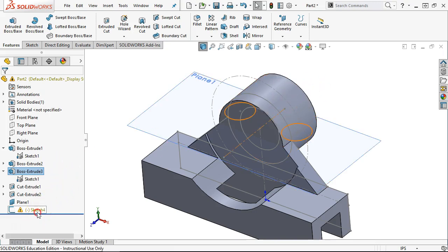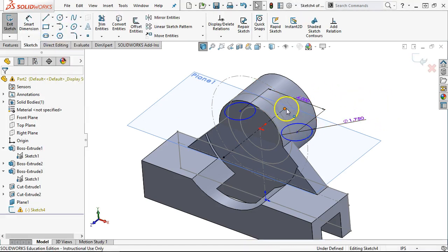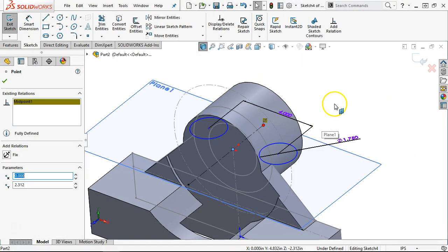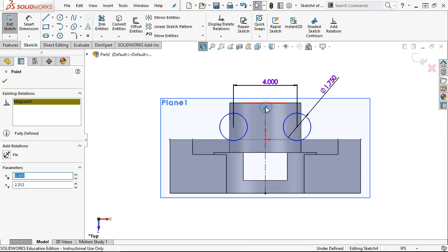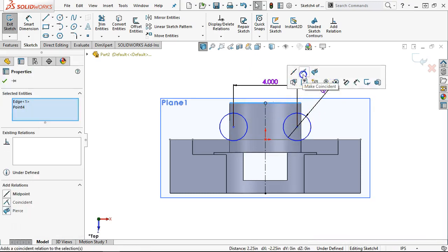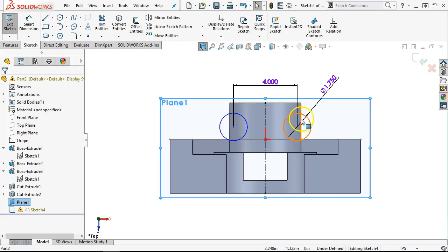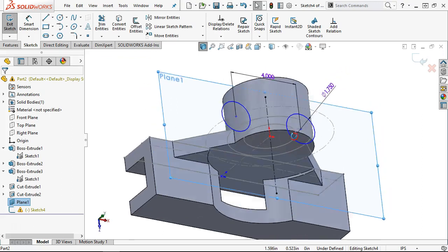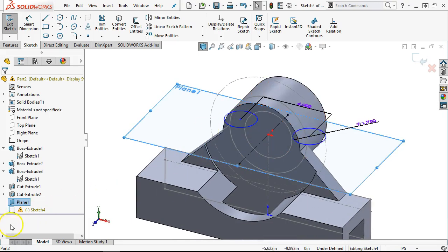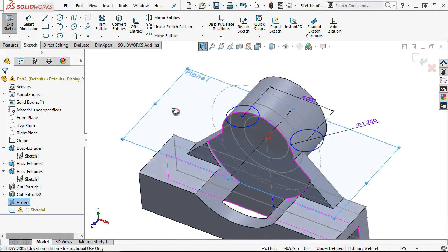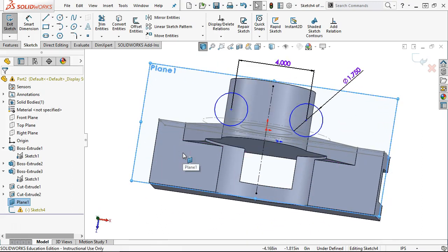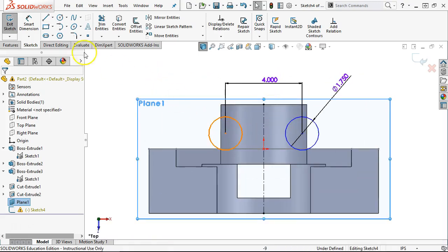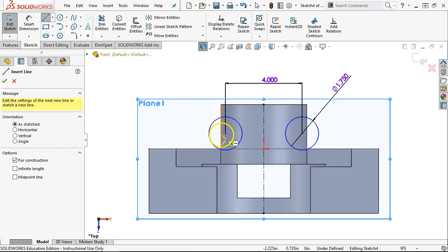Well, not surprisingly, the sketch picked up because that geometry changed a little bit. I'm going to end up with one dot in amber because that midpoint now is not able to calculate. So we'll just delete it. It can go back to being coincident. Don't really care where it comes back to. So we left off with 4 inches, and then we're pretty much centered. So the 1.63. Yeah, the tough decision is, am I going to be able to pick up a midpoint?